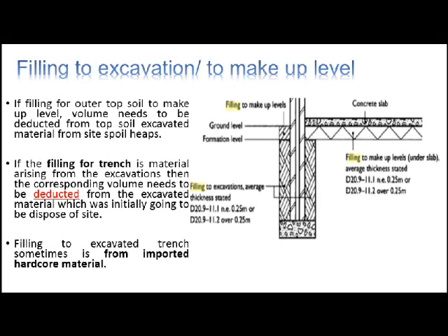Once you do the excavation, of course, you need to fill them back after you have put the item there, like the foundation is already poured, the brick wall in the substructure already constructed, then you need to fill back these trenches.